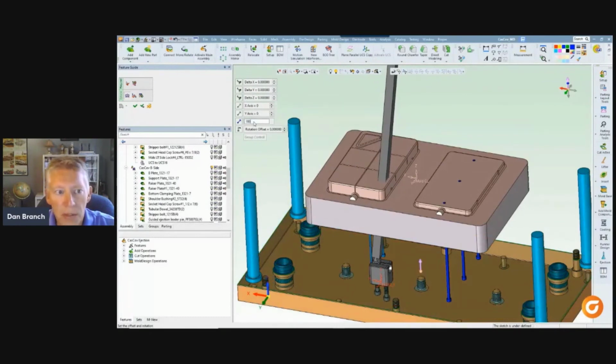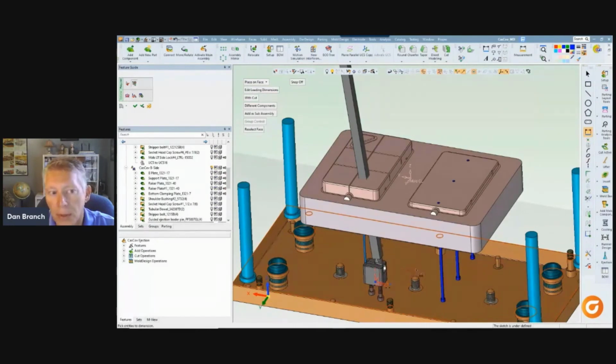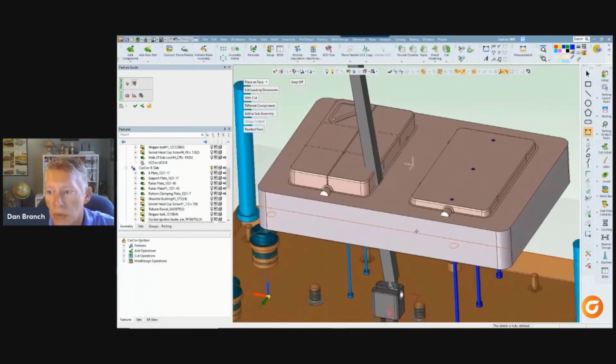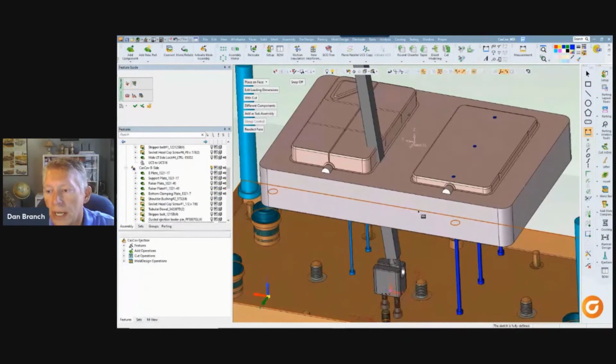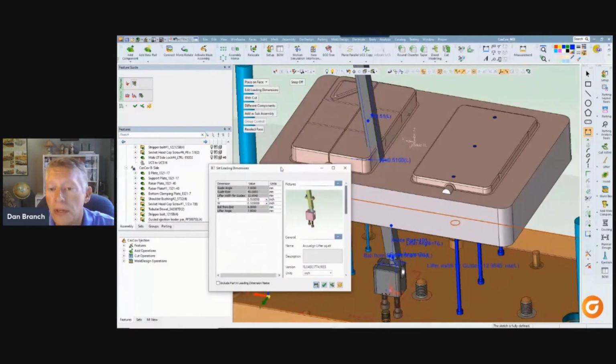Because a lifter mechanism like this has several important parameters and they all work closely together. So far, I'm just seeing a preview of a certain size and it may look pretty good, but there are a few things I can make obvious adjustments to. And that's all in one handy catalog table. For example, the lifter angle. So that's related to the depth of the feature being molded, of course, but I know I can get by with just 5 degrees in this case.